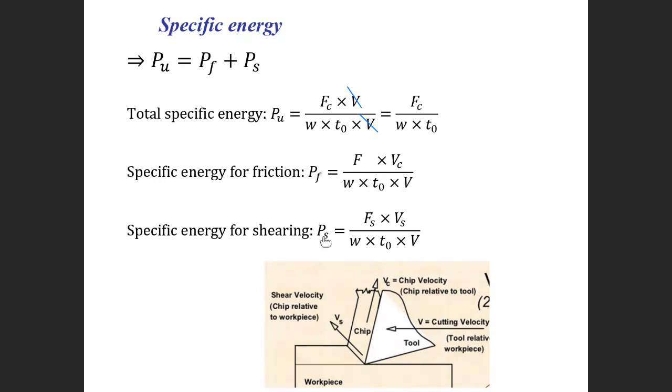Those are different. And the unit power in shear equals Fs·Vs, the shear force multiplied by the shear velocity, divided by w·t0·V, where V is the cutting velocity.